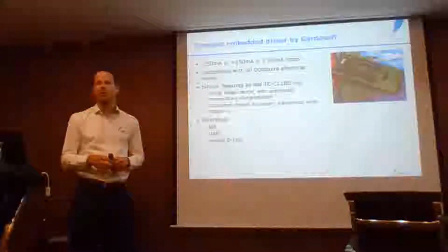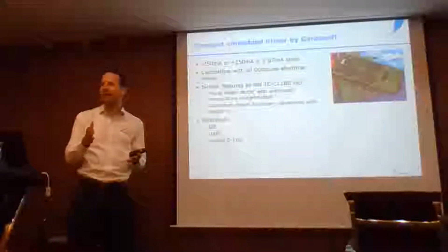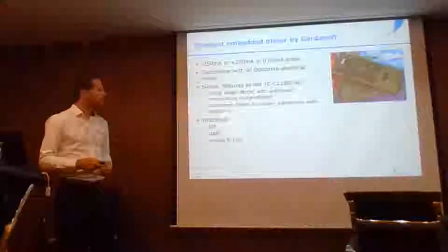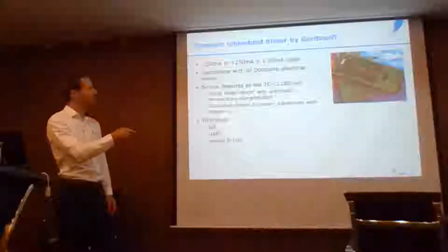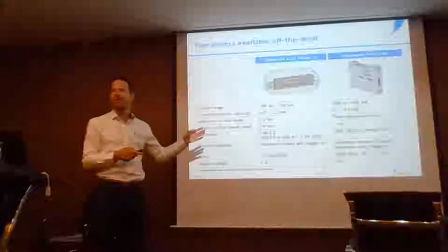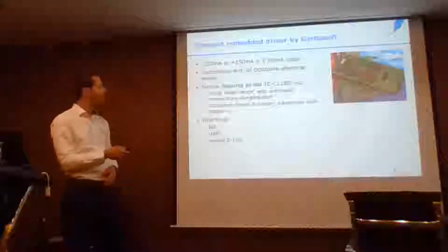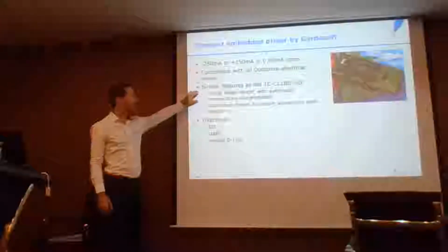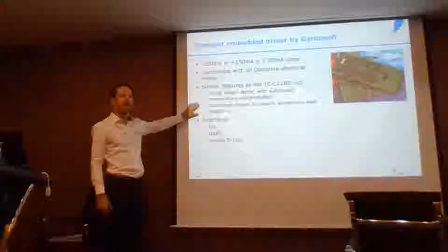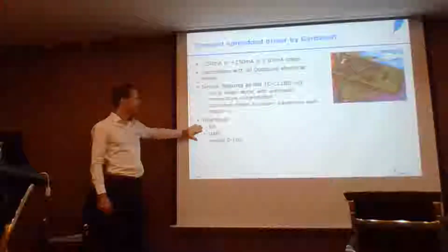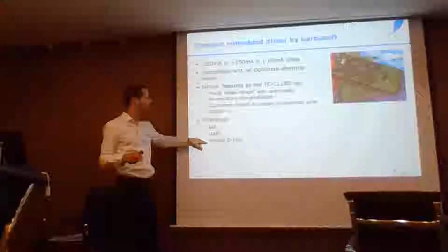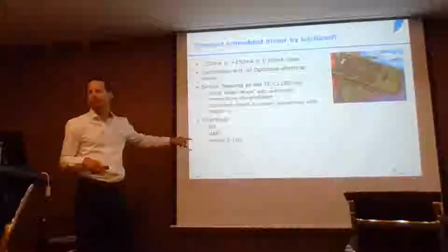The license model is not quite fixed yet, but maybe something like a flat fee, depending a bit on the volume. You have maybe some flat fee to pay. But then we can have actually the same quality of the large driver, the same features in this little driver. And so it has the focal power mode with temperature compensation. It has the same waveform options and the analog input option. And the interface to control it is mainly I2C as a digital interface, or the analog in stays the same.